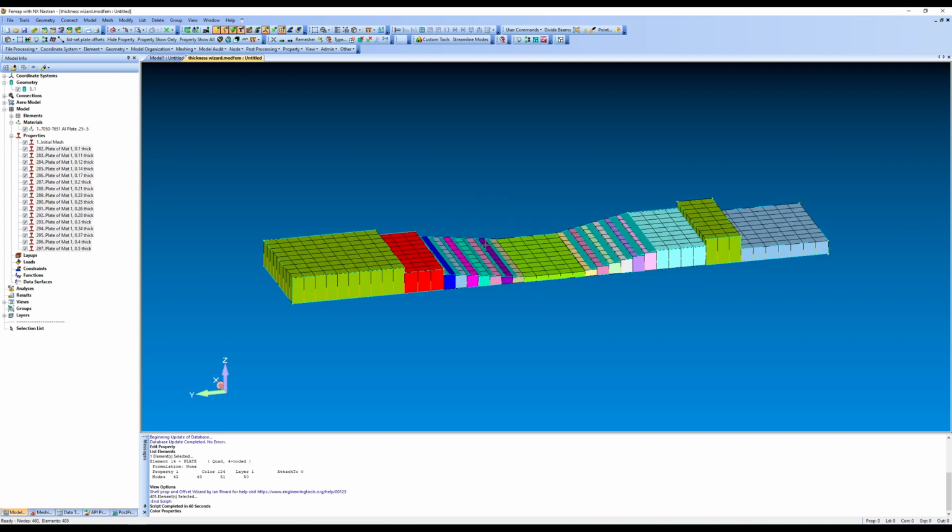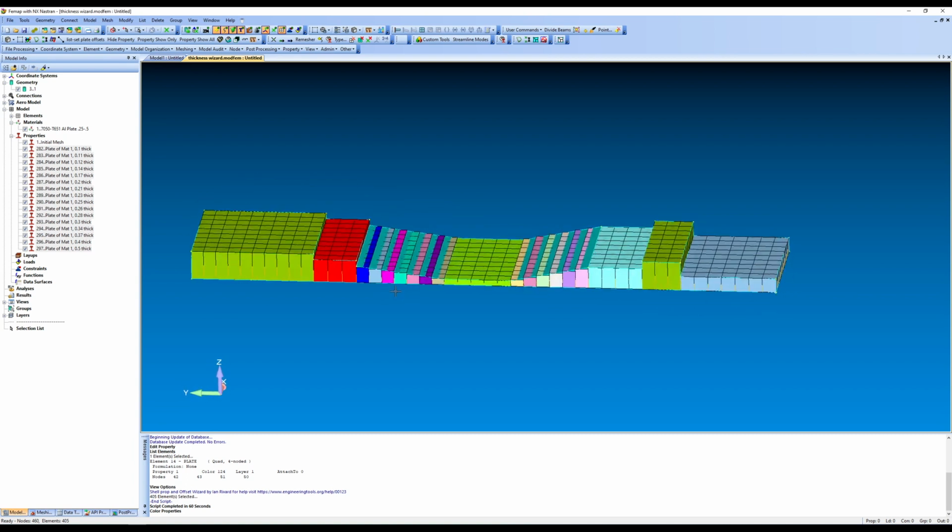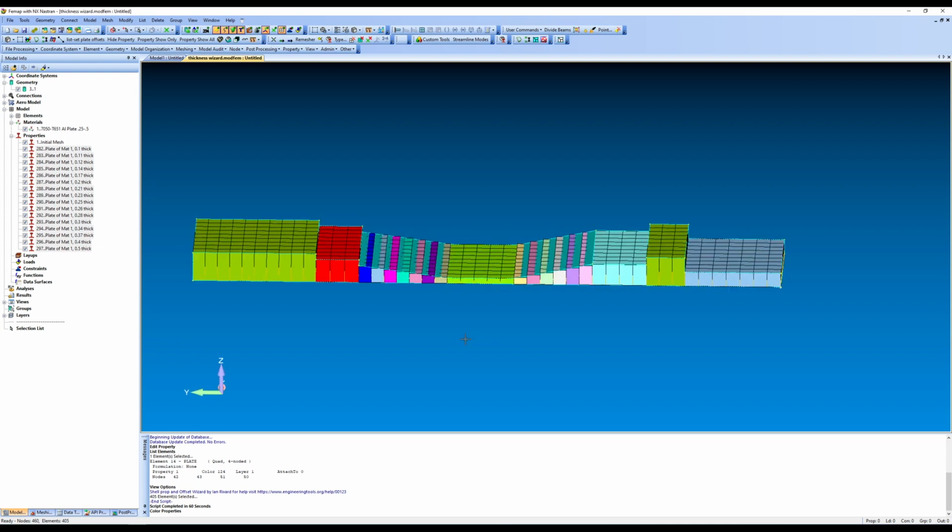We can see how it came up with the thicknesses. So it looks pretty good. It matches the solid pretty well. Here it looks pretty good. If you need a higher precision, you can add a higher mesh density. You can remesh these, or you can switch to corner thicknesses.